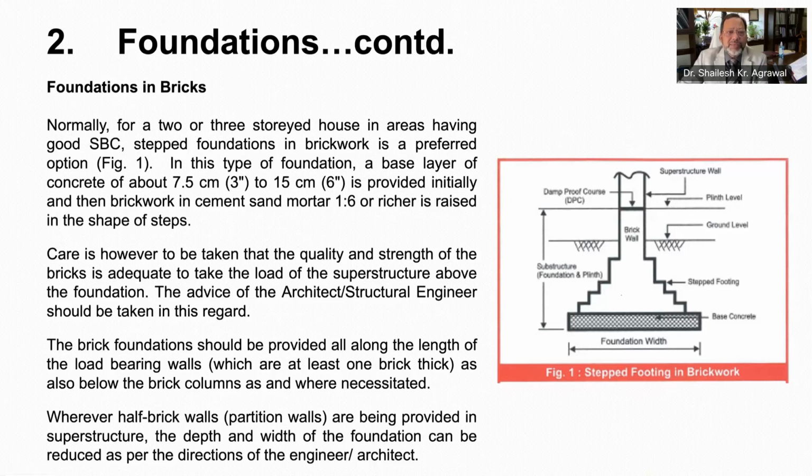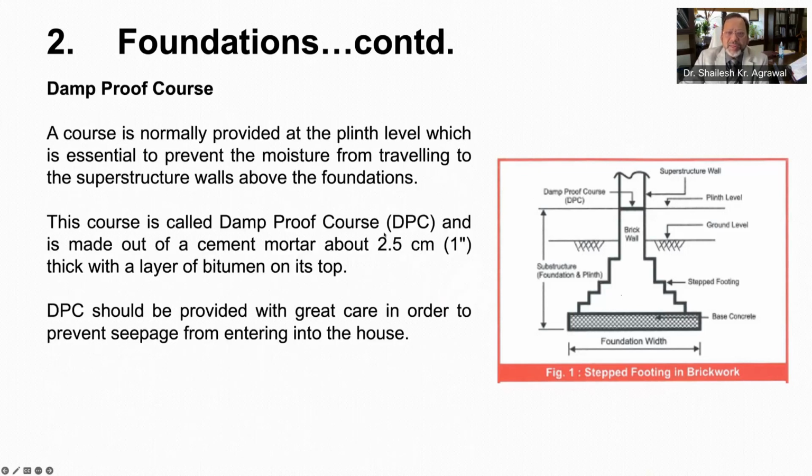However, my advice is that engineers and architects need to be consulted for foundation design, and utmost care should be taken to use quality and strong bricks. Another important aspect while constructing foundation is damp proofing course, which is a barrier to prevent the moisture from traveling to the superstructure walls above the foundation.